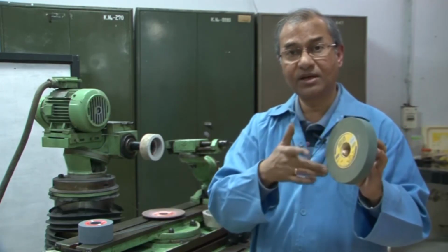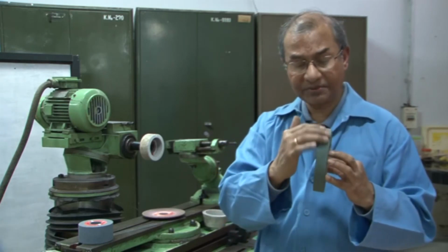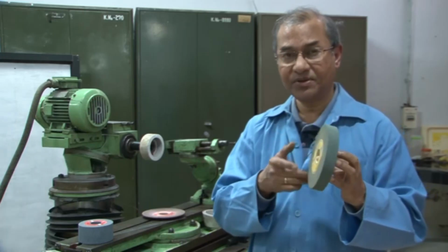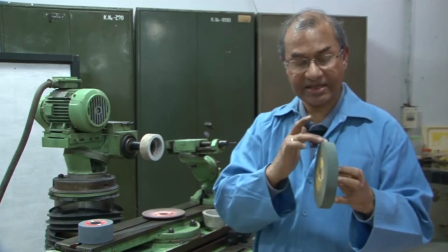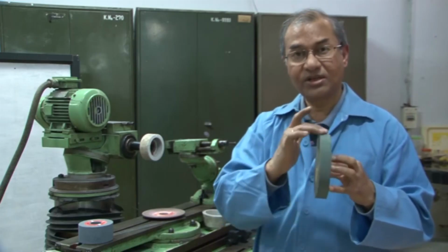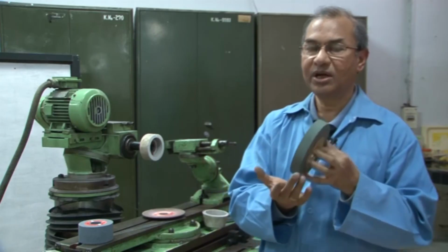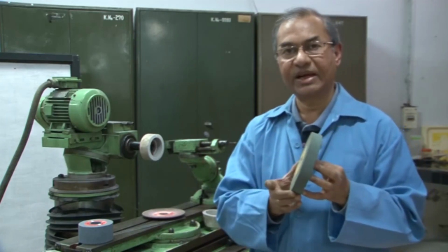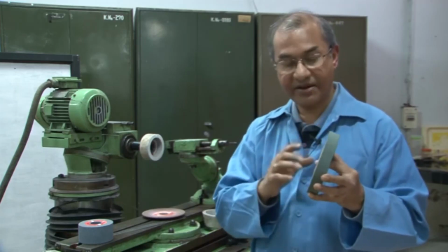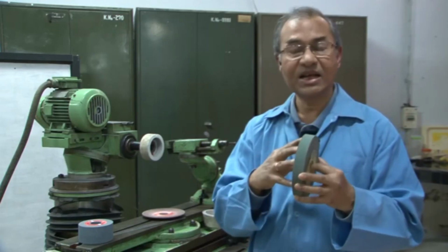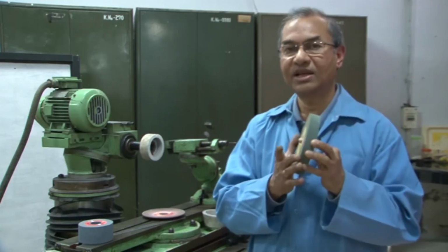those chips will be nested, and instead of the grains cutting the workpiece, removing the workpiece material, the nested or clogged chips will be rubbing, and that will also consume more power. It will rub, and the force will be taken more without removing much of the material. So, that is also a negative factor, like in the case of wheel glazing, but in this case it is called wheel loading, that the wheel has been loaded.